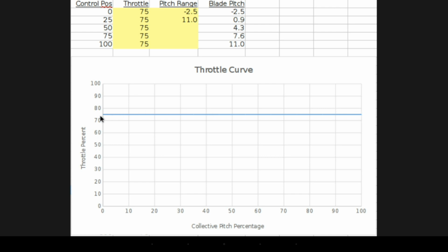The governor will use this, your electric governor. So this basically, for all practical purposes, duplicates what mode 2 does. You can set these points to 80%, 85%, 65%, whatever you want, and it will just create a flat throttle just like the mode 2 set point does. So the mode 2 is pretty much redundant from that standpoint.